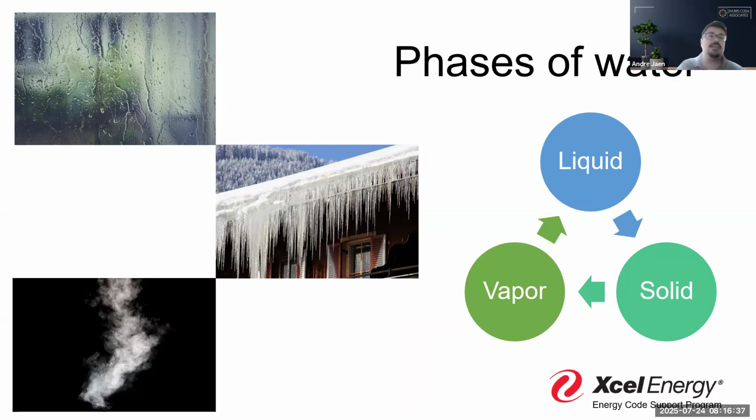Our materials are designed to fight this intrusion because we know once it gets in, it just keeps repeating on a feedback loop, right? Once we get liquid water in and it freezes, well, water, when frozen, expands, right? Once it expands, it creates a bigger hole. Once it creates a bigger hole, we can get more water in. Once more water is in, it's going to freeze again, right? It just keeps going on this loop where it's going to create this problem in perpetuity.